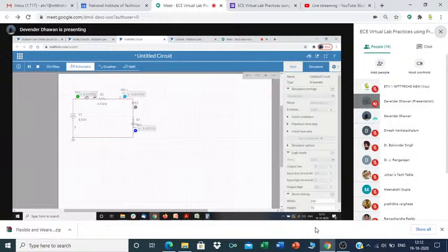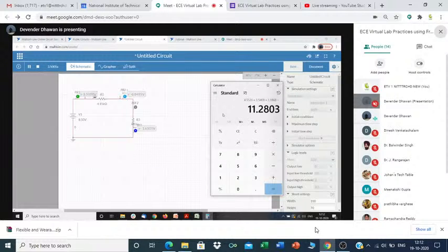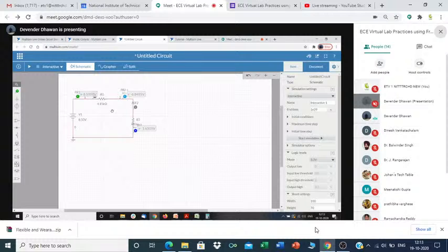So you can see 8.5, then this is minus 6.8495 and minus 1.6505. So let us just sum it up once. So minus of 6.8495 minus 1.6505, which is minus 8.5, which is what this is. So 8.5 minus 8.5 is 0. So again, the KCL also holds here, and both the basic laws are working. So this proves our KCL and KVL.